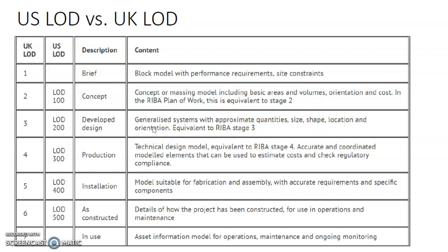And in the production stage, you are talking about LOD 300 or the UK level 4, where you have the technical design model. Accurate and coordinated model elements that can be used to estimate cost and allow regulatory checking and compliance.